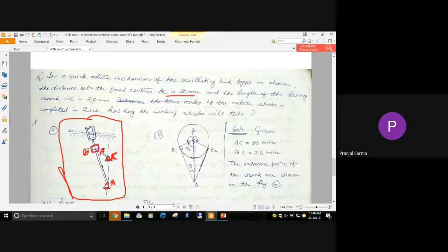Now in this portion, whatever the cutting tool is, if you connect the cutting tool here, this is how it is going to have the motion along this side. In the forward stroke it is going to cut, and the return stroke should be idle, but it should be accomplished in a faster way. That means it will be a quick return, taking less time in the return process. The forward stroke actually cuts the material, and it is accomplished at a somewhat slower pace.